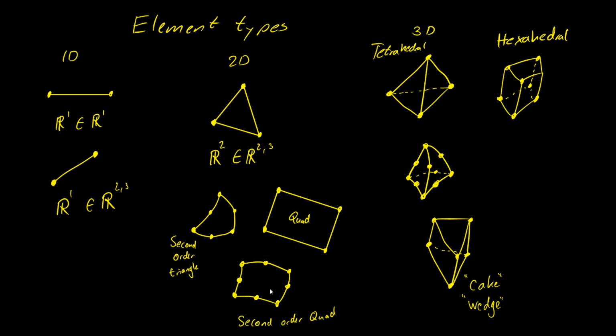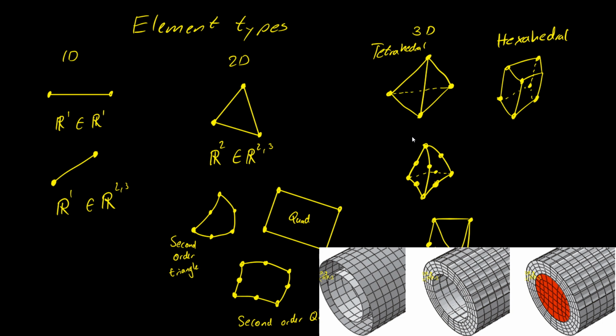The reason we have these flat elements, where the thickness is 0, in 3D is to simplify the computations a lot. Because the alternative is to use three-dimensional elements in order to model something very thin. And that means you need to have a lot of elements. Remember, these things can't be squished too much.